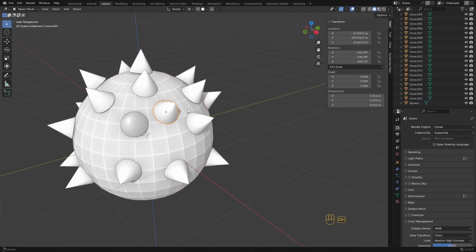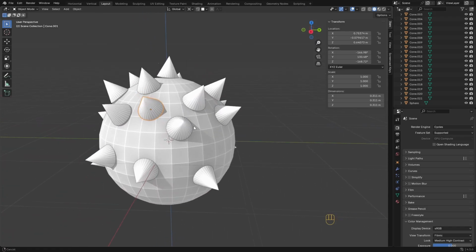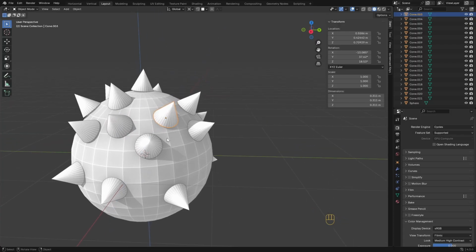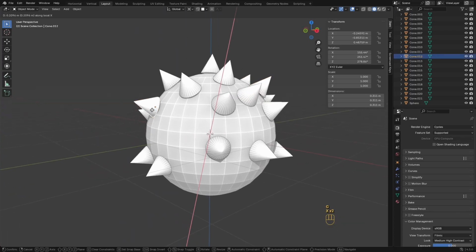But now, if I grab, for example, this one, I press G and then Z, it says that global is not matching. But if I just press Z again, it says that it's local Z-axis to work in this direction. So it's actually useful. It's good to understand. So G, Z, Z. You have to press 2 times until you get it in the right way. G, X, X.